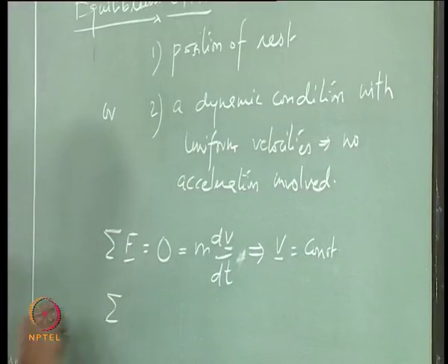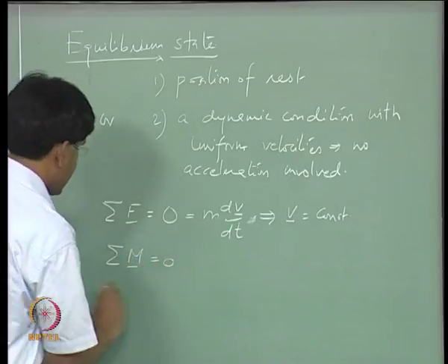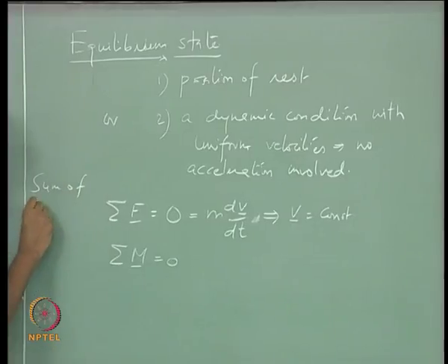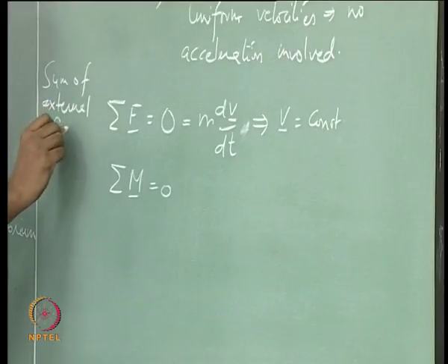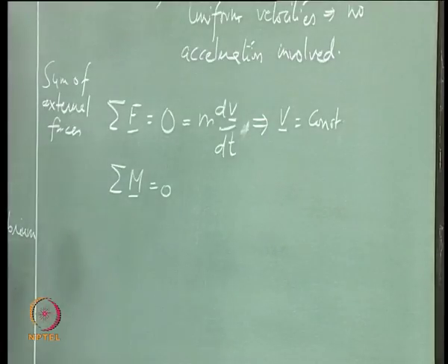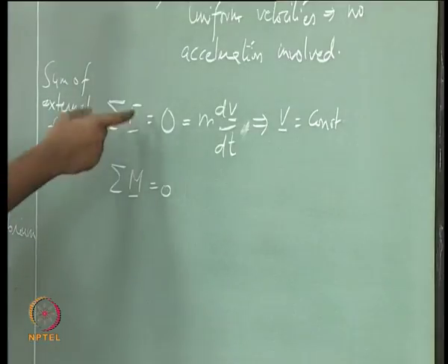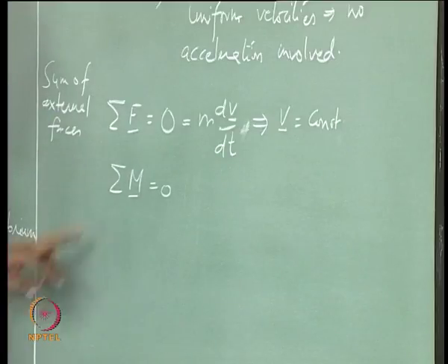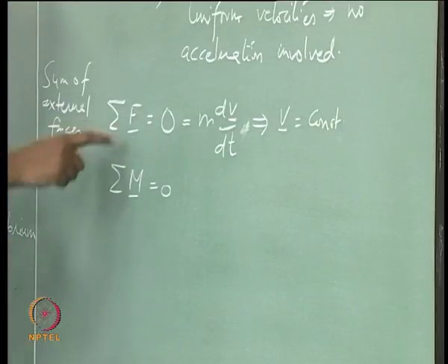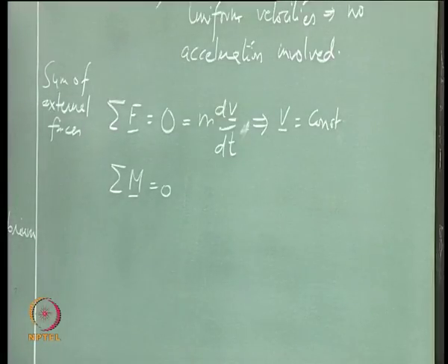Added to that, we should also have this condition satisfied, because the aircraft is having 6 degree of freedom motion, 3 in translation described by these 3 force equations, where F is a vector consisting of the forces along the 3 axes of the aircraft, and the moments which result in 3 angular motions of the aircraft.